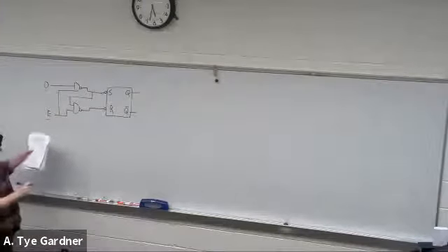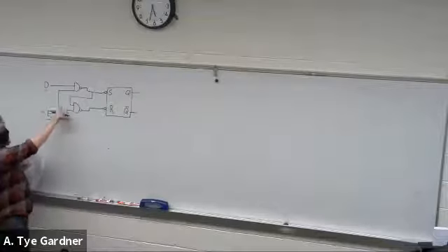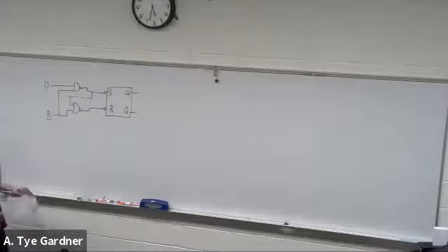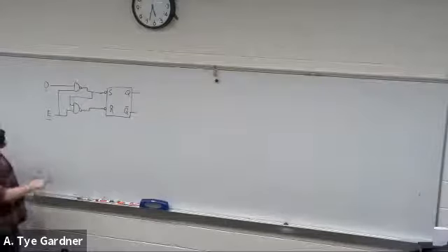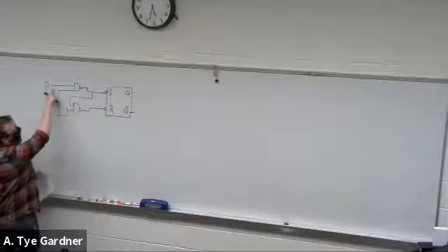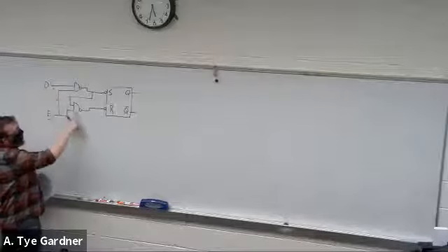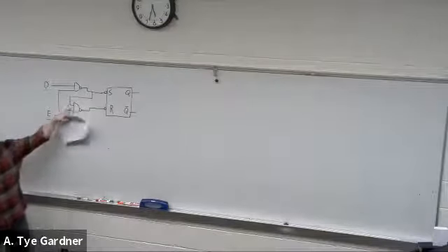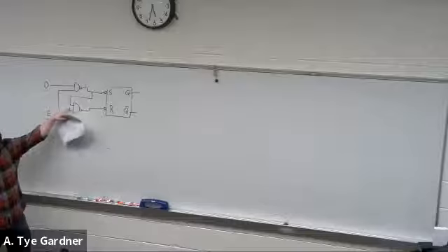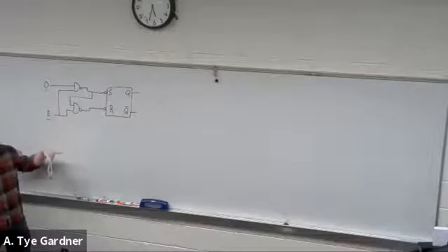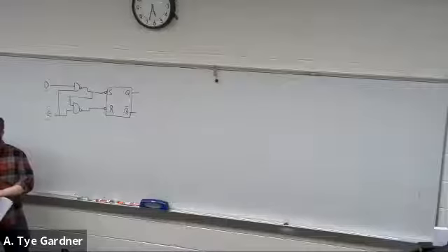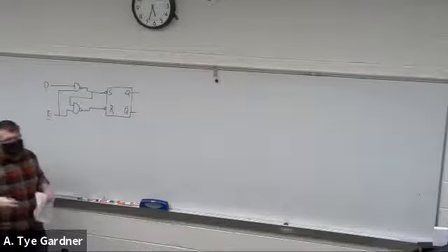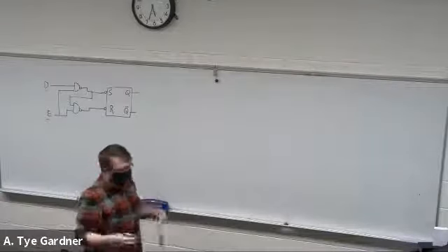And now, this is a little bit easier to deal with. There's no inverter here. Simpler circuit overall. And now we can do a little bit of analysis on that, right? So what's happening here is if the data is 1, we're guaranteed to not set and reset at the same time by having this feedback into the NAND gate. There is a little bit of a delay there, but it's kind of convenient the way it works out, because then you will never have that switch at exactly the same time, because you have to use this delay path and then this delay path before the set and reset. So it's predictable. It doesn't go into that kind of not quite stable state.